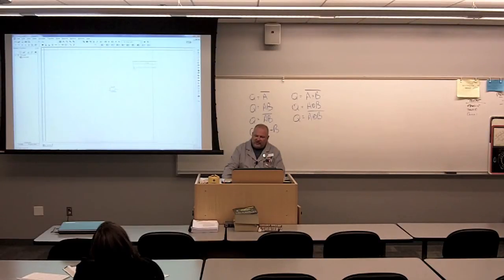It's this logic converter. So I select it and then I drag it over here and I place it. When I double click on it, left double click, it opens up the logic converter and I can actually see my inputs. I've got inputs A through H and then I have an output.